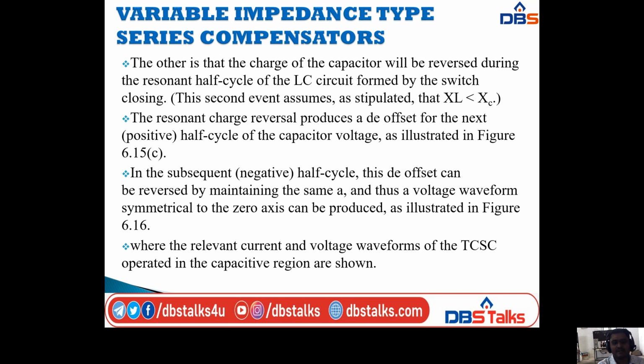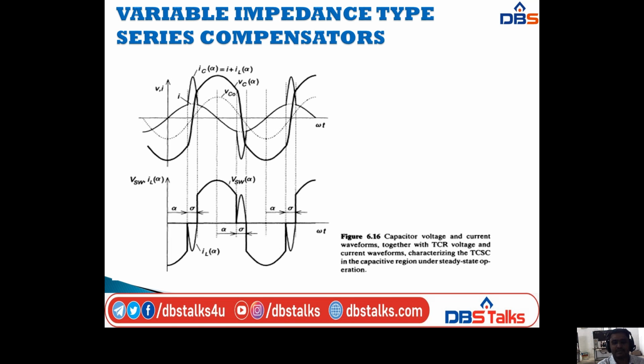In the subsequent half cycles, the DC offset can be reversed by maintaining the same alpha, and thus a voltage waveform symmetrical to the zero axis can be produced. That is shown in figure 6.16. This diagram gives the capacitor voltage VC and current waveform I, together with the TCR voltage and current waveform, characterizing the TCSC in the capacitor region under steady state operation.